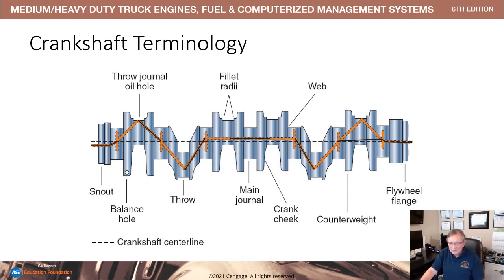That hole is designed to transmit oil. We have oil galleries in the block that connect to the main bearing surfaces, so the main bearing surfaces will be pushing oil through to the mains and the connecting rod. All of the journals on this crankshaft are rifled or oil gallery connected together, so we have a film of oil on every critical surface in this crankshaft.